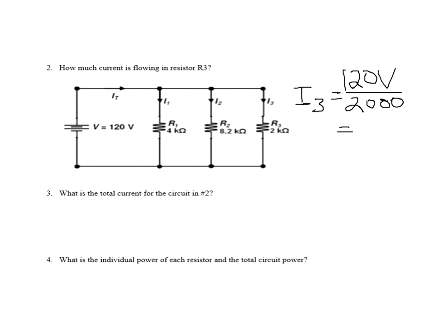All right, what is the current there? Let's get the calculator out and check it out. All right, you should be working these with us together. 120 volts divided by 2,000 ohms. I got 60 milliamps for that one.